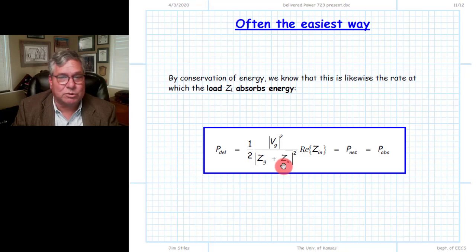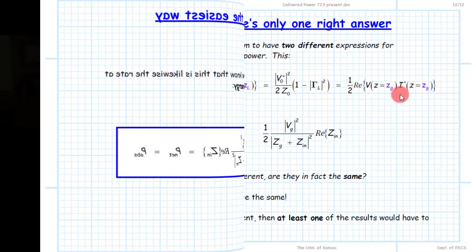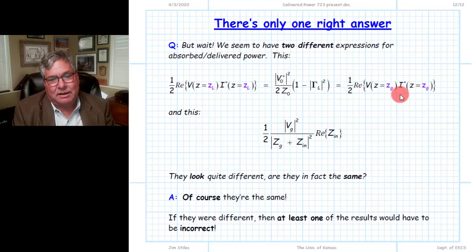Find the power delivered from the source using the equivalent circuit. And once you have that power, you can usually go and figure out then the remaining two values of incident power and reflected power. To emphasize again, all of these methods provide the exact same number. All of them are valid. Again, we choose the one that is easiest for us to calculate, generally speaking. And most of the time, that is the fourth method that we discussed here, where we replace a large portion of the circuit with an equivalent circuit, and then simply evaluate the simple equivalent circuit that results.